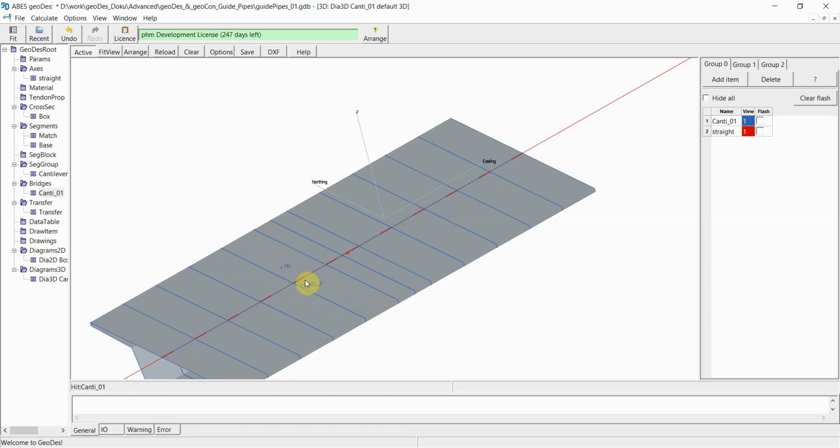Both the global point and the line are defined in global coordinates, and no matter what the correction will be later on and what the adjustments will be in the casting yard, the setting out data for these points will be prepared in a way to ensure that these points will end up in their required global coordinates as specified for the global elements.